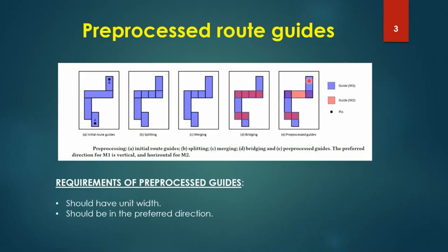So what is the good thing about that? The good thing is that, say if you had this as the route guide, this is actually the non-preferred route, and this will be in parallel with the upper routing guide, that is metal 2. So this will actually form a parallel plate capacitor with the metal 2.